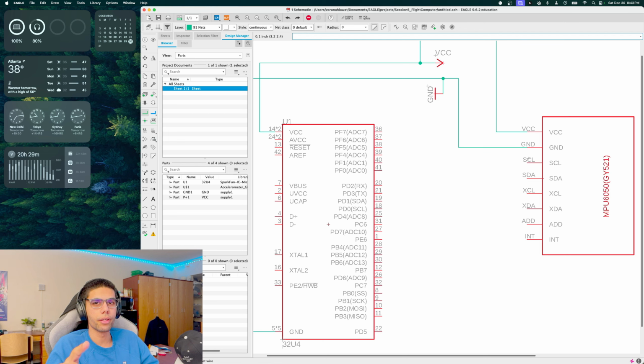So this is SPI, if you remember. We studied SPI yesterday, which is a serial peripheral interface. This is one of the 3 or 4 communication protocols that I taught yesterday. I mean, in the last session. So serial clock allows both of their clocks to be synced together so that they could share the data. If you remember the clock signal, that's the heartbeat of both of them, basically. So they must be in sync. So this allows their clocks to be synced.